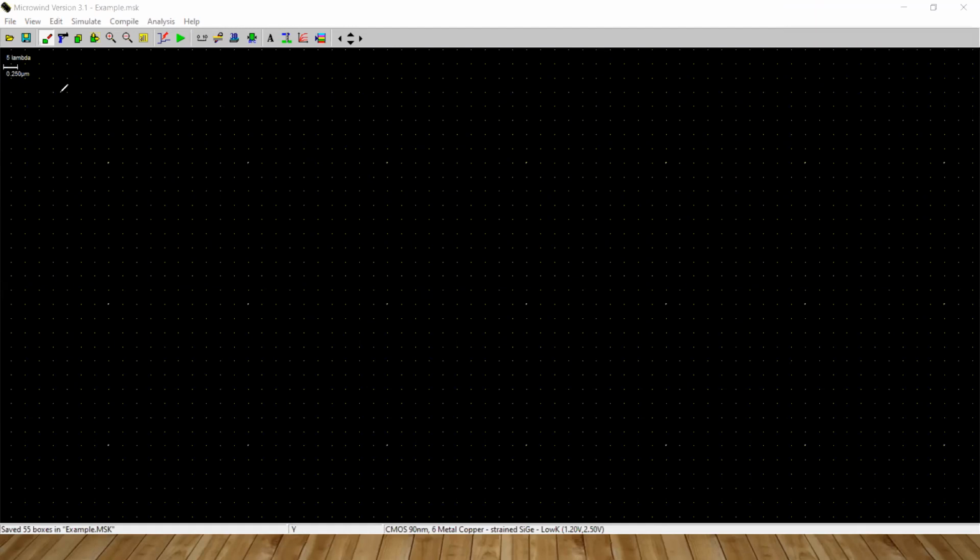Okay, so similarly, towards the source of the NMOS we have applied VSS, that is ground. Within the N well also we can apply ground? Below, you are asking, right? No, there is no need to apply VDD because it is a P substrate only. So in case of PMOS only we need to apply within the N well, right? Yes, only PMOS, because it should be reverse bias. So it is N well, so apply VDD. That will be reverse bias.